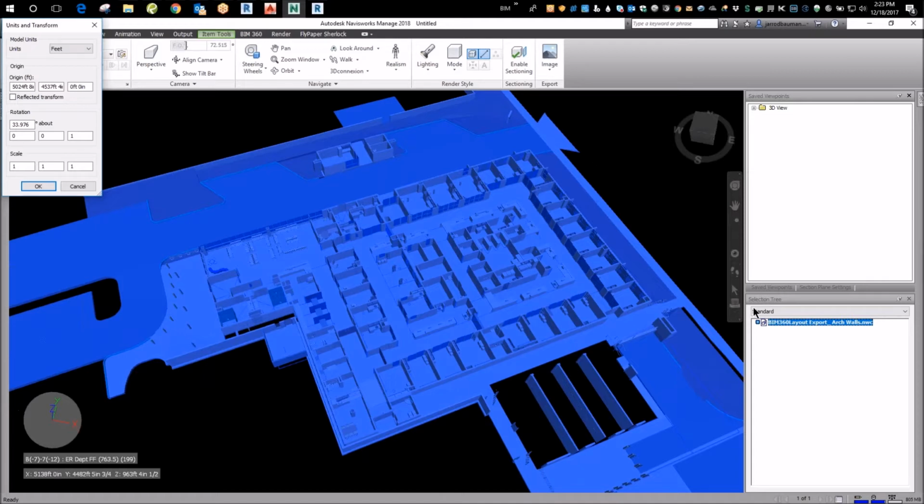Okay, so this is important, and we're not going to get into the conversions of units, but for example, in AutoCAD, a civil engineer draws very large stuff, right? Sometimes entire city maps. So they use a unit where they say, when I type in 1 inside of AutoCAD, I want that to be a foot. I don't want that to be an inch, because now I'm going to have to type in bigger units, right? So they use one unit equals a foot. What do architects use? Quarters, eighths, sixteenths. Well, they use inches.